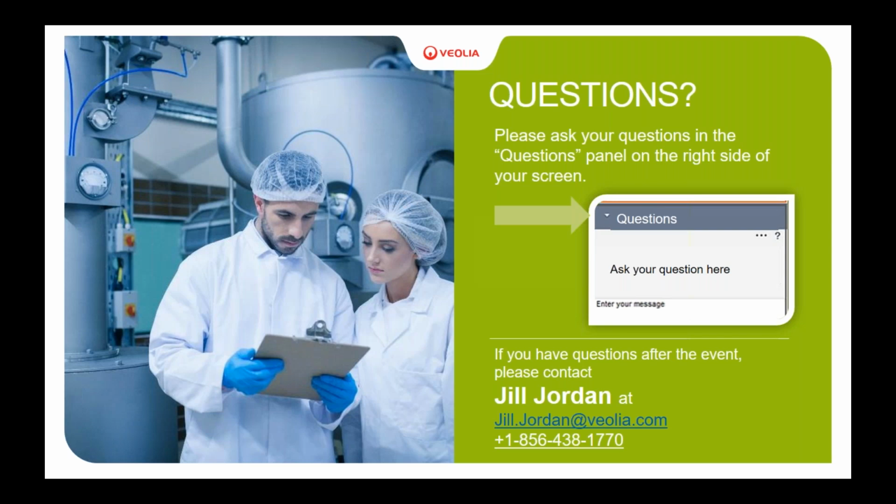And I completely agree with Jill on the calamity. We see sometimes not just a 1,000 times increase in a certain parameter with a dump for 2 hours. And it's not just the anaerobic system. I mean, if there is a dump of FOG, your average FOG is 1,000, and then it comes in at a 10,000 slug for a couple minutes, your DAF chemistry is going to go off. A lot of processes are going to be interrupted.